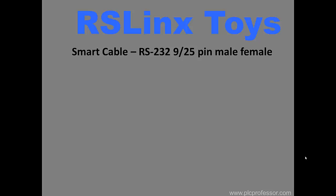Okay, RSLinx Toys. There's a thing called a smart cable. The folks that have been around for a while, they've probably seen one of these. It's like a switched breakout box with LEDs and a ribbon cable, and on the end of the ribbon cable it has 2 25-pin sub D shell connectors, 1 male, 1 female. Then on the actual adapter, the converter, or the pinout box for the LEDs, it has another 25-pin D shell. And then you use combinations of 25 to 9 pin, male, female.